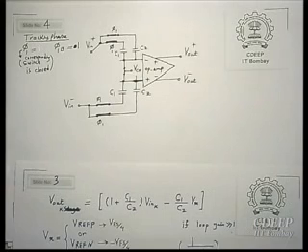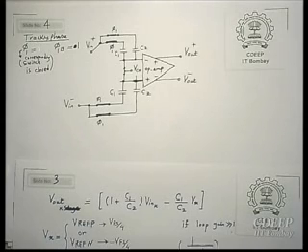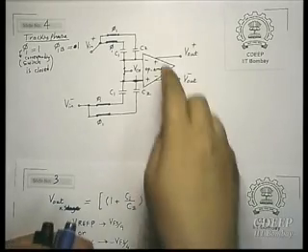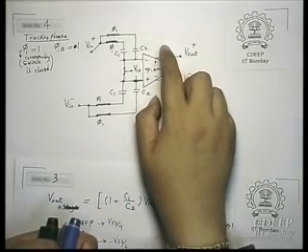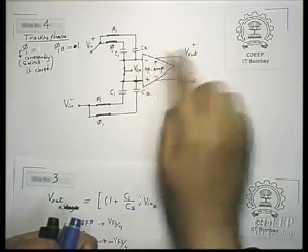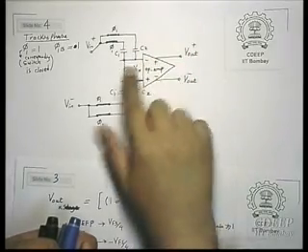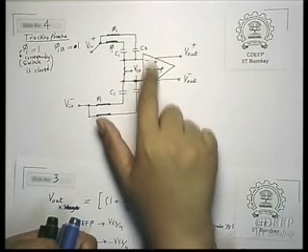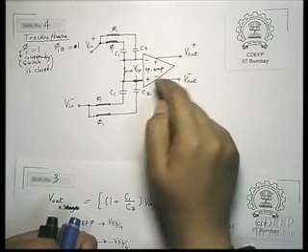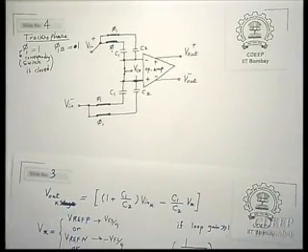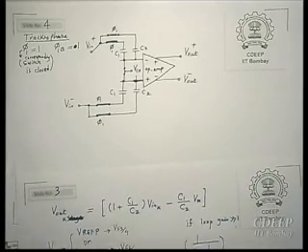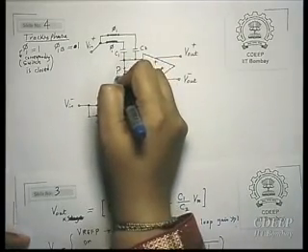Actually, it was my question, why they have done this. This doesn't look right, I don't know what the reason behind that is. Because we would prefer to put the 2 capacitors in the feedback loop, or rather, not capacitors, just a direct connection, unity gain feedback, remove this connection, and then this is an Opamp, therefore inputs will get connected to the common mode internally using common mode feedback, then you will get it. I don't know, maybe their Opamp, so you check this from the paper. So this will remain a question mark, okay? Why do we need this? Because this doesn't solve the problem of offset.